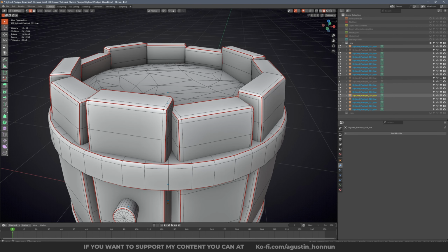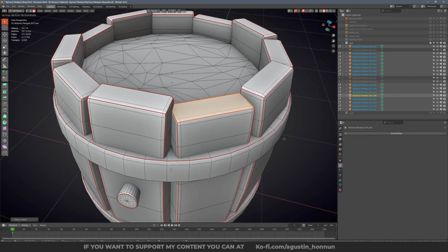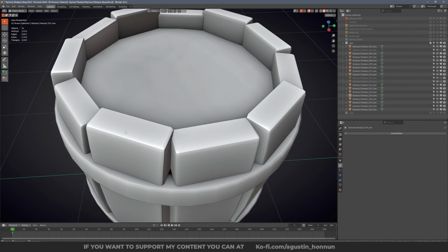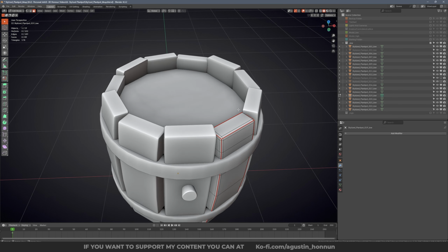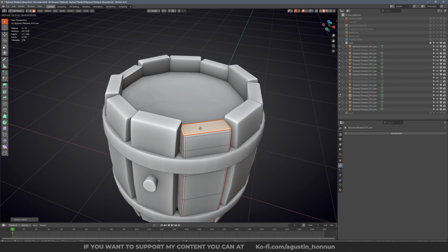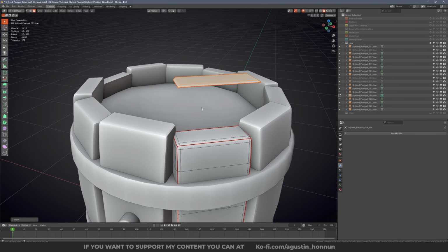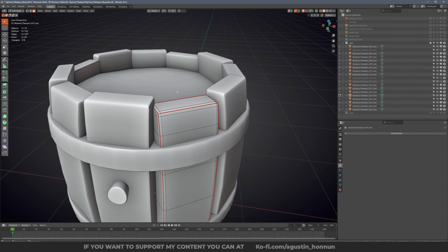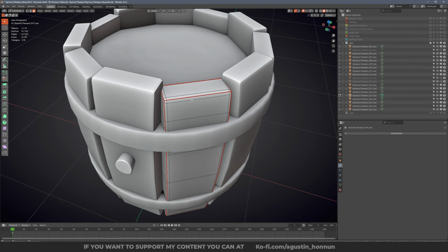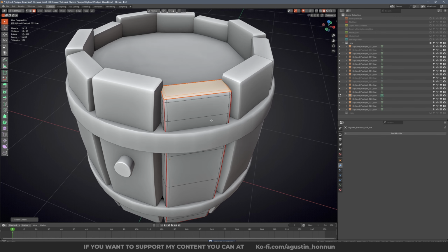For example, if you select this face and you press Shift D and duplicate this, and you leave it like that, you may not notice there are some duplicated faces. But if you select this and move, there is another face in the same position. So that will be a big problem, since we are going to have some big issues there. So that's why we select everything and merge by distance. As you can see, we remove the duplicated vertices.